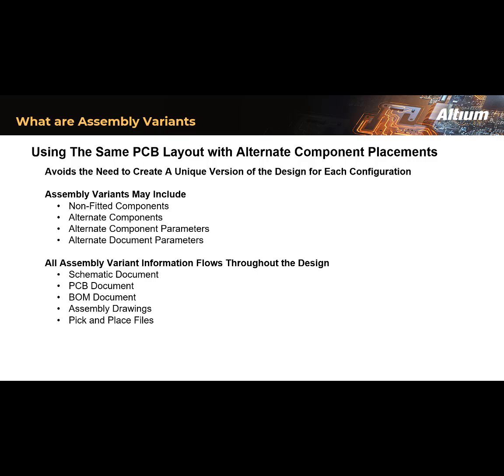The ability to create variants of the base design adds some pretty significant flexibility to how PCB projects are created in Altium Designer. When using variants, you can define any number of variations to the board design where each component may be configured as fitted to the board, not fitted to the board, a completely different component, and each variant can also pass parameters down through the entire project.